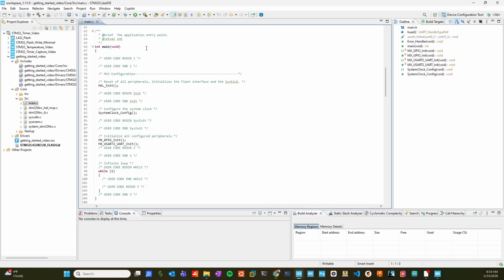And so in a subsequent video, we'll talk about how you modify this, how you talk to the board, and so that we're going to use this little debug thing here, not the run, but the debug. So we're going to debug by basically compiling this down to an ELF file, and then sending this across something called an ST-Link, which is a piece of software, and it's also the name of the debugging hardware that's on the Nucleo board.